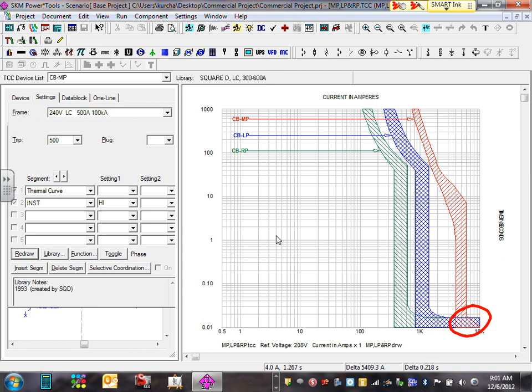If I'm working in this panel, and I took phase A, phase B, phase C inside the panel, and put them together, then flip the switch, the main of this panel and the main downstairs will trip. How often does that happen? Only probably 1% of the time, if even. Most of the short circuits that you encounter, like you said, Jeff, are covered in this area.